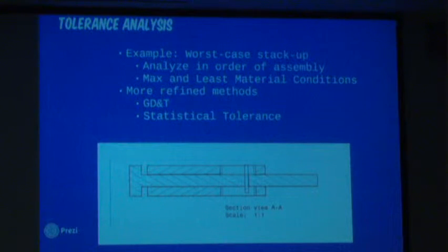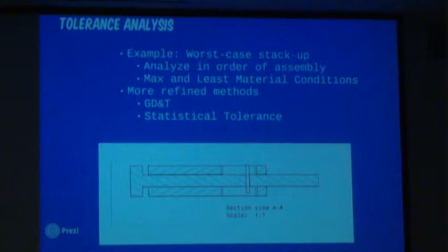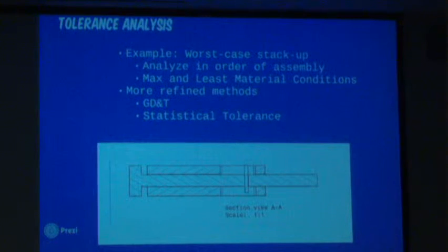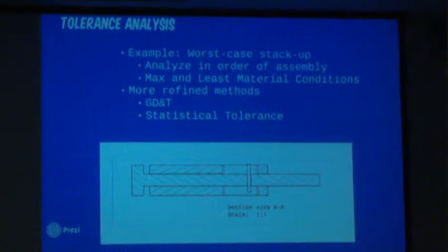Okay, so you'll know what the mean and what the tolerance is on a given machine that you make parts on, and you accept that risk that they could not fit together based on the statistics that you have. So you may say, I'll allow 1 in a billion combinations to not meet. If you're making a medical device, you never ever want that to happen, so you'll use worst case. Right? So if you're making somebody's pacemaker and they're going to be in surgery and they're going to put two parts together, they better go together every time. So you'd want to use worst case.